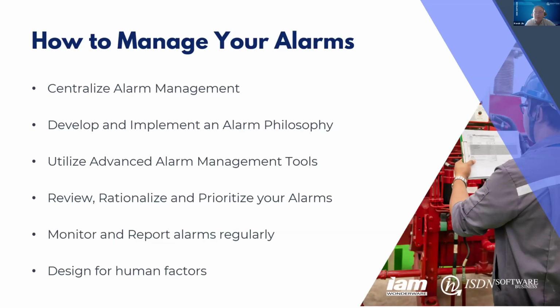So having such tools will help you review alarms that happen so frequently, rationalize them, and understand what they mean. Like, okay, I understand that this alarm happens often. This is a nuisance alarm, so I can put it aside by reducing its priority, saying this is not as important.